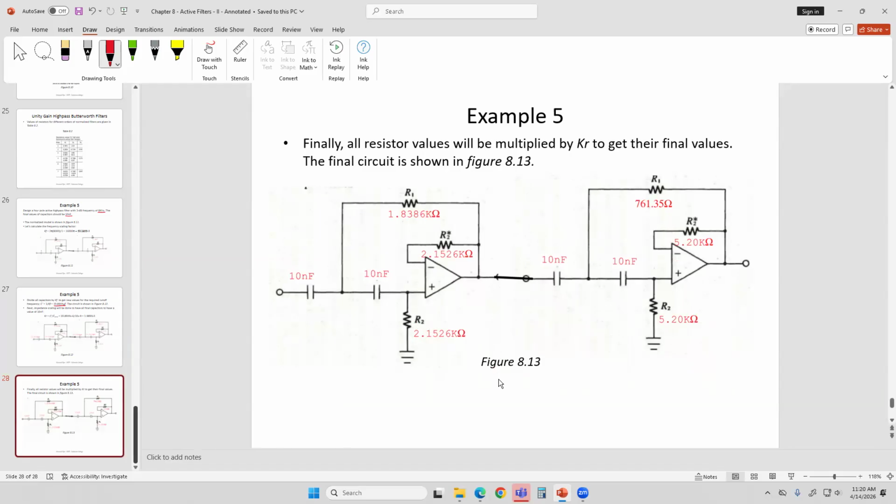And again, if you want to confirm if your values are correct, that depends on the cutoff frequency, remember. So you create your circuit in piecewise, you give an input, connect your AC supply at the input, perform the AC sweep, and then observe at 8 kHz, you should have 70.7% of whatever value you're using for your AC sweep. If you're using 1 volt, that's going to be 0.707 at 8 kHz from this circuit, and that's what you're doing in the lab as well. So the design is very straightforward.